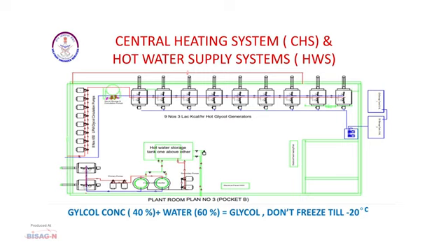Now these boilers heat up this media of glycol and send it through a circulation pump to the building, and in the building this glycol, which is at a temperature to the tune of 70 degrees, through fan coil units transfers the heat to the room. This cooled off glycol then again comes to the boilers, gets the heat and keeps circulating in the loop. There is certainly loss of the glycol in the system. Now this loss needs to be taken care of, otherwise there will be airlock.